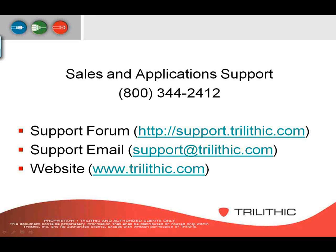Let's see, there was a question about the FEC not helping with live video, so when we troubleshoot video on demand issues, do we focus on the pre-BER? That's always a given. Always focus on the pre, whether it's video on demand or your regular digital, because that's where that actually shows you your actual impairments. So you always want to work off of the pre's.